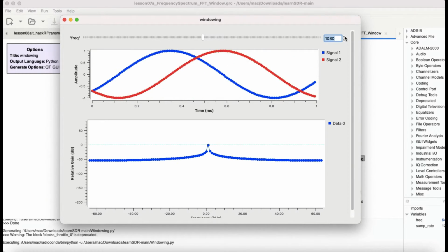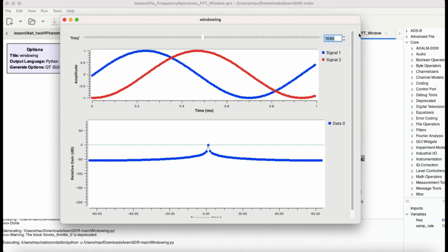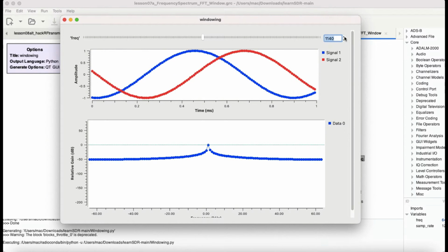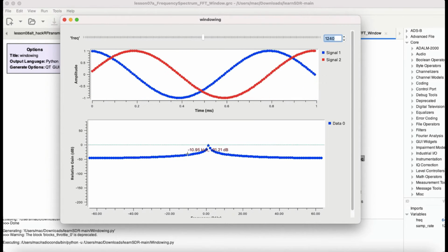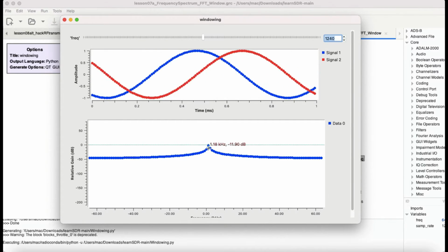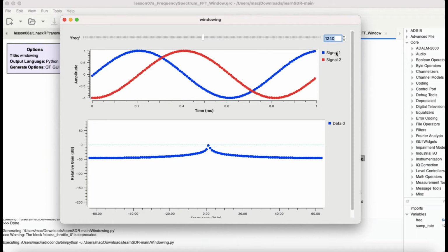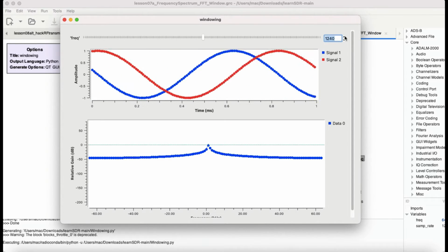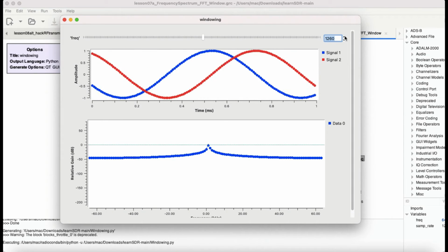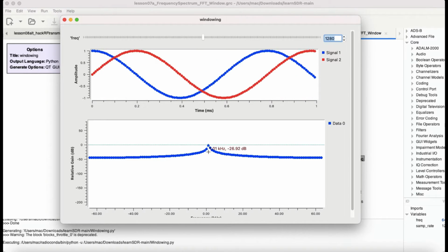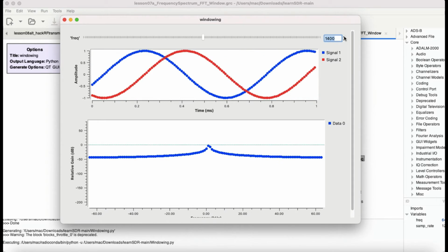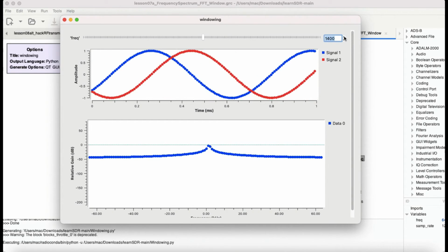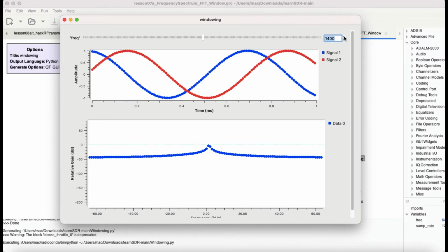Just quickly observe this. Observe it right over here at this point when I'm changing my frequency. Now when you look at this, you see this? Now my noise floor has jumped tremendously. These side lobes are getting bigger and bigger, and my main signal, the main spike, is actually changing. I'm using a rectangular window, which is a general window right now. So when I change this, let's observe this right here at this point. Now when I change this, you see this? Now the bins start getting closer and closer. You start acquiring the next frequency bin.